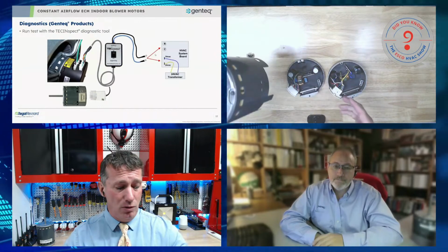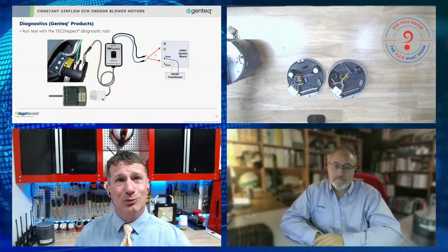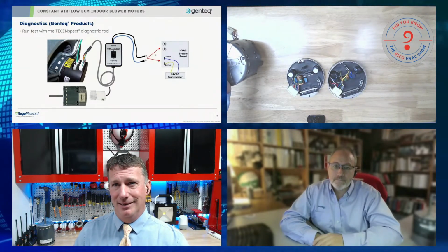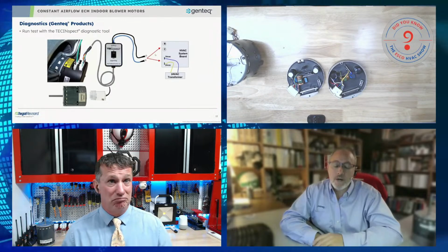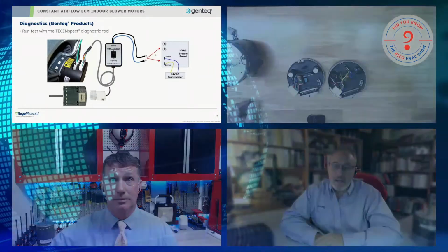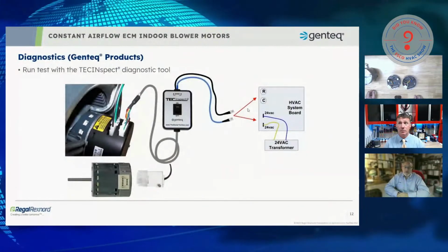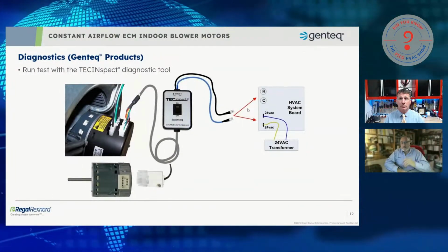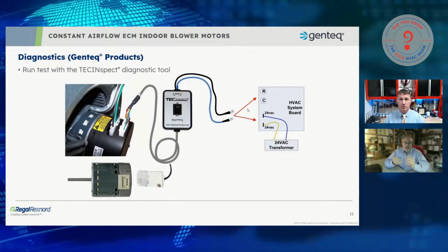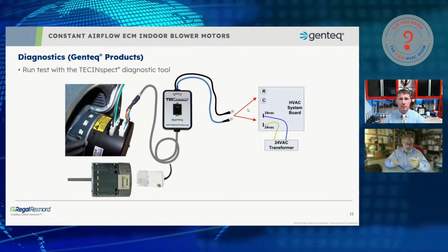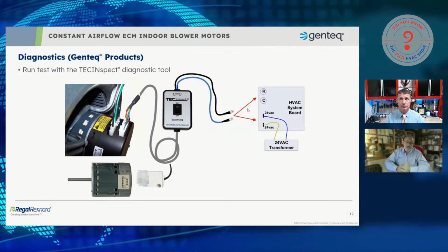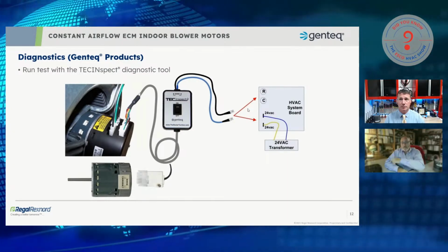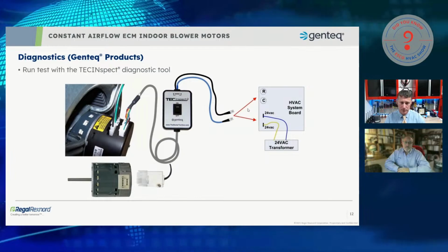So the go, no go is very important because it tells us really, is our mod turning on our motor? Is it giving it a command? Correct. And I'll take that even a step further. It's not only is it a robust motor, but you have a microprocessor in front of the motor. We got a microprocessor with a speed limit. And, you know, we talked about the inrush thermistor. If that inrush thermistor fails, that's protected the motor windings from getting to a point of failure.